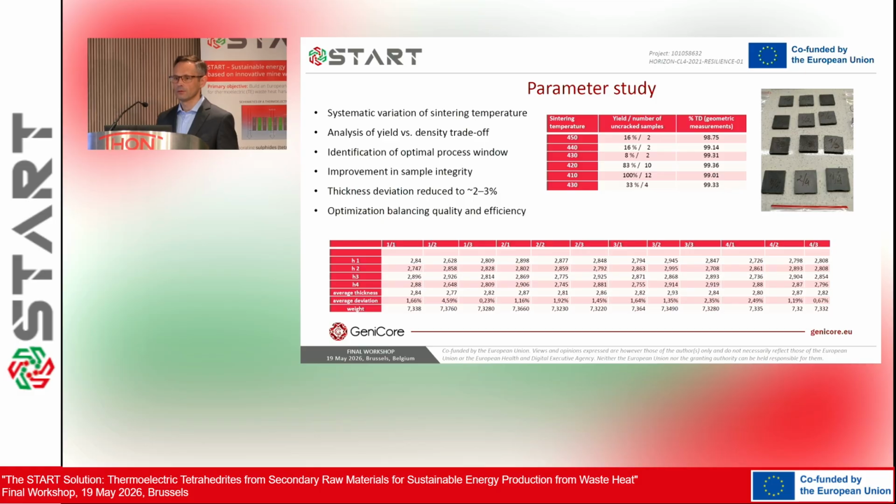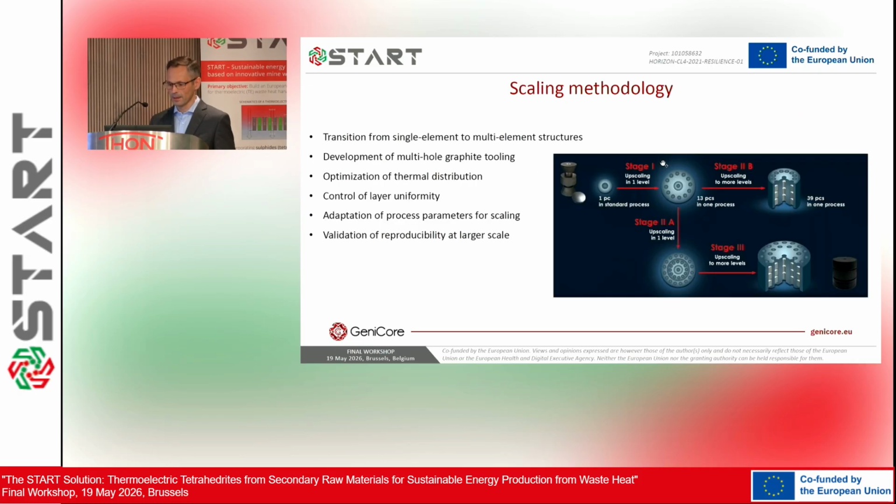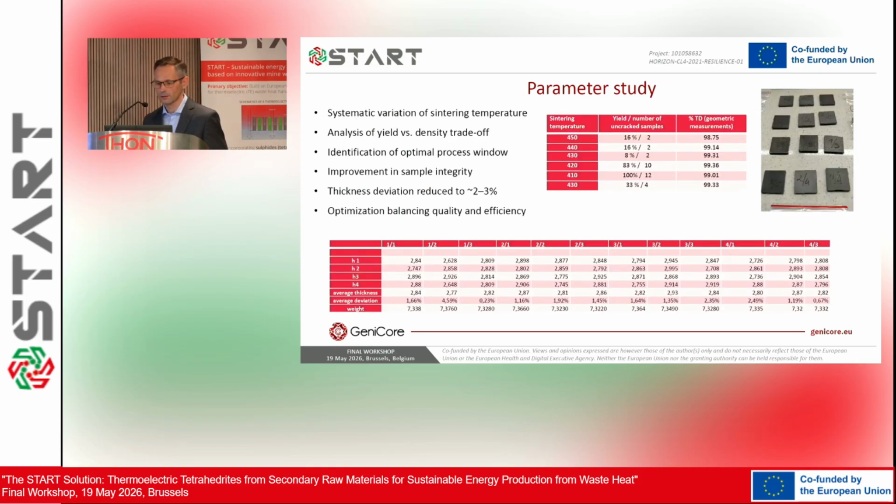As I mentioned, not only the sintering process is crucial, but also the cooling stage. Here is an example of different yield from the process in relation to the cooling stage, which is divided into cooling with a specific rate. Finally, cooling of the order of 15 Celsius degrees per minute was applied, and an additional annealing stage around 300 Celsius degrees.